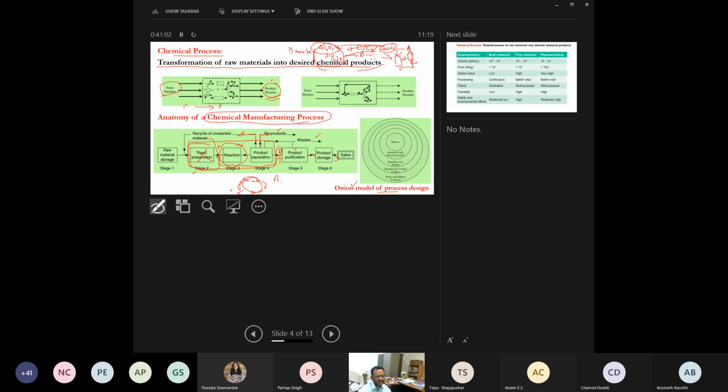In wet grinding, normally the temperature of the sodium hydroxide has to be around 60 to 65 degrees centigrade, so you have to preheat this. You can use the heat coming out from these pressure vessels, or flash drums. Here the heat recovery system is essential so that we can minimize the utility requirements, so that your operating cost will come down.